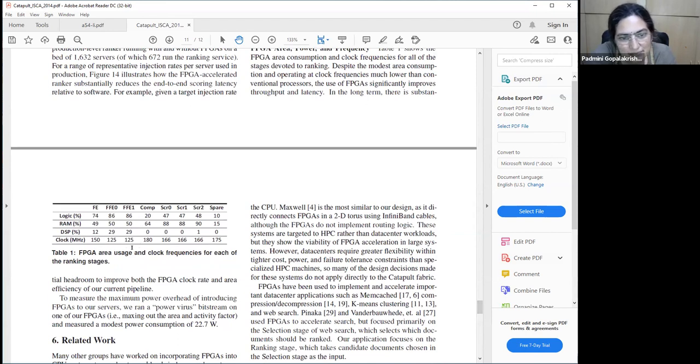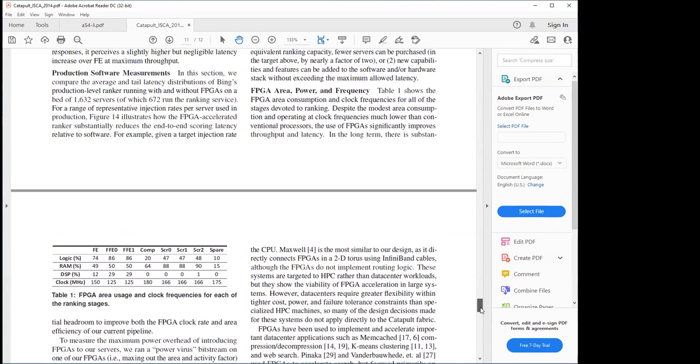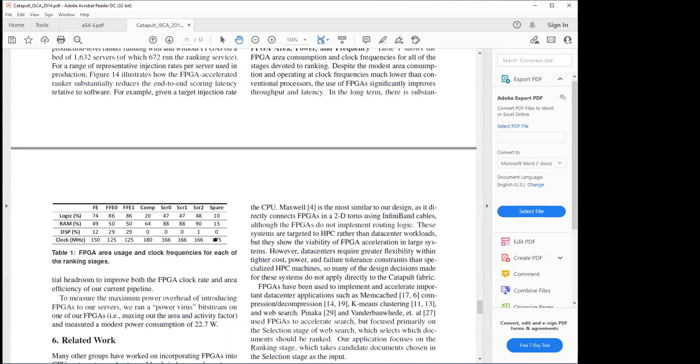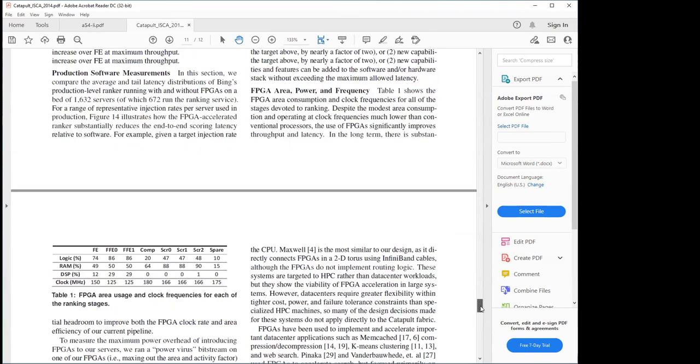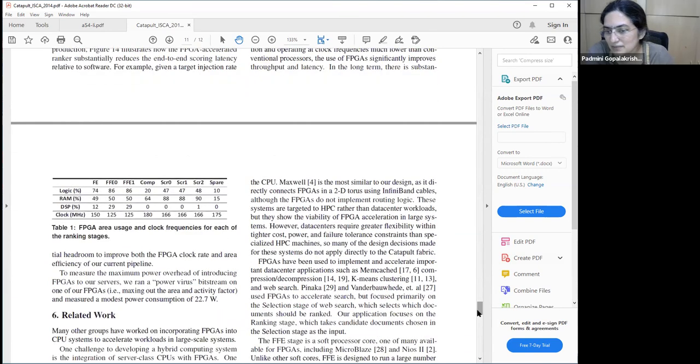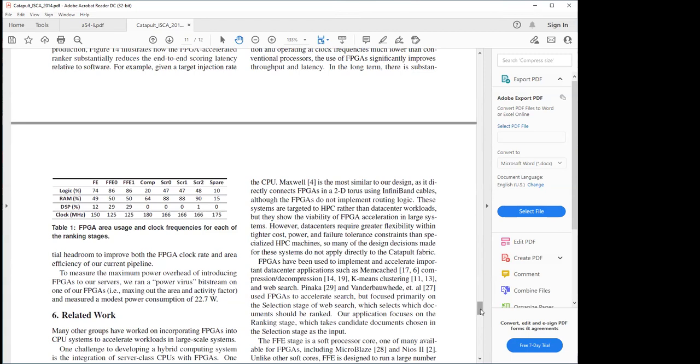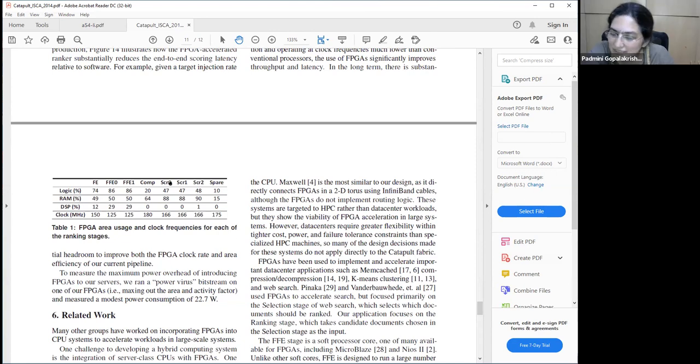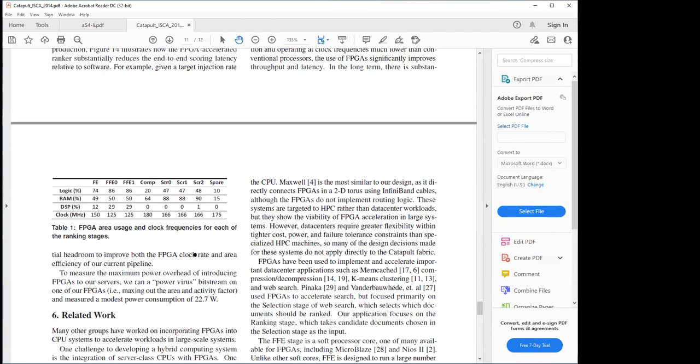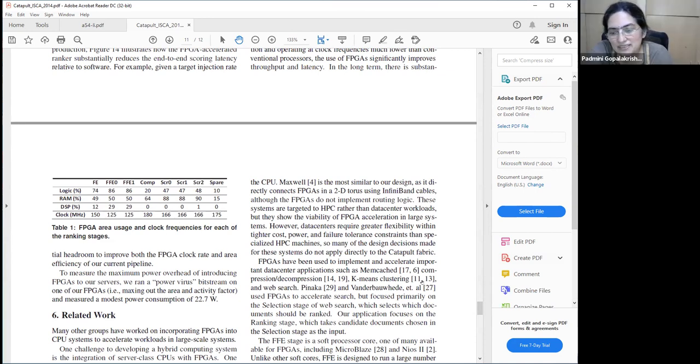You see. Hmm. So is it the same even for DSPs also? Like if you use 100% DSP, will it be hard to get timing closure? Yeah, depending on whether the data path going through the DSP is critical or not, it could be. So we definitely see challenges there. When you get the RAM and DSP utilization to be very high, especially RAM, because RAM, when you use it heavily, almost always tends to be on the critical path, especially for these types of applications. You're bringing data in and out. So those tend to be difficult.